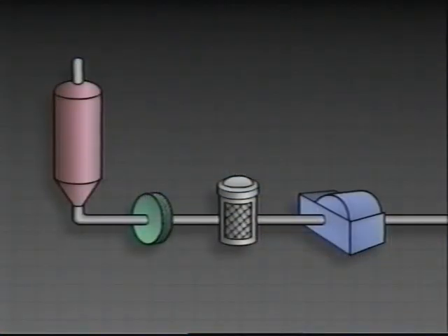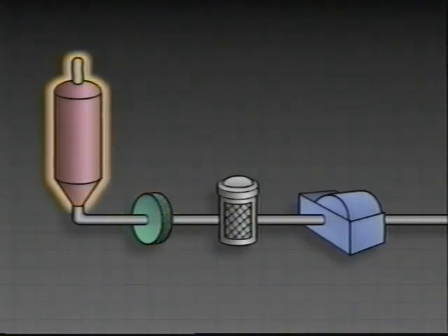In the pulp mill, there are several factors that can cause a high debris level in the pulp. It could be a bad screen, perhaps, with a hole in it that allows debris to pass through. Or it could be a refiner with worn discs, which don't shred the wood fragments enough and leave too much debris in the pulp. The problem could also be abnormal operating conditions in the digester, such as improper cooking or poor steam circulation.